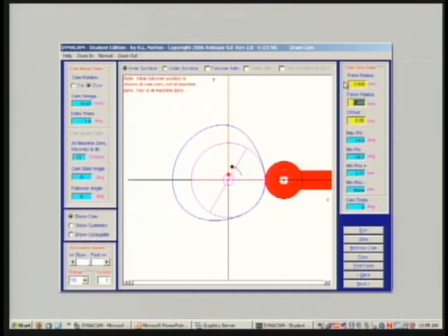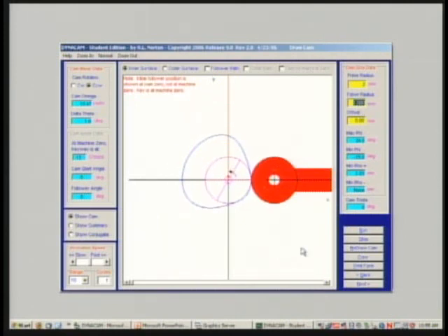Let's see what happens if we make this prime circle radius smaller. Let's cut it down to 2 and see what happens. It recalculates. You can see now the roller looks ridiculous with respect to the cam. I now have brought my pressure angles up to 20 degrees, which is still perfectly acceptable. My radius of curvature has come down to 1.83. Still acceptable, it's 1.8 times.